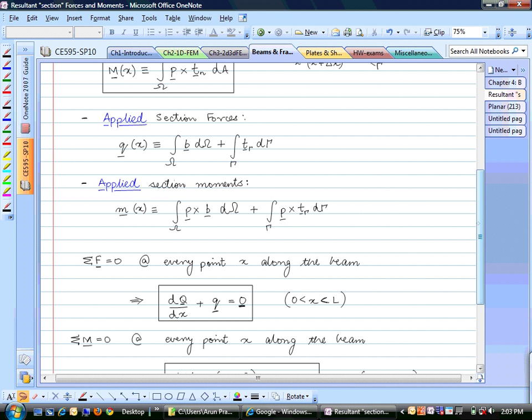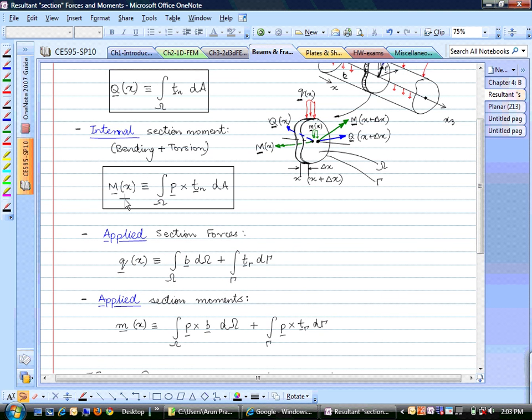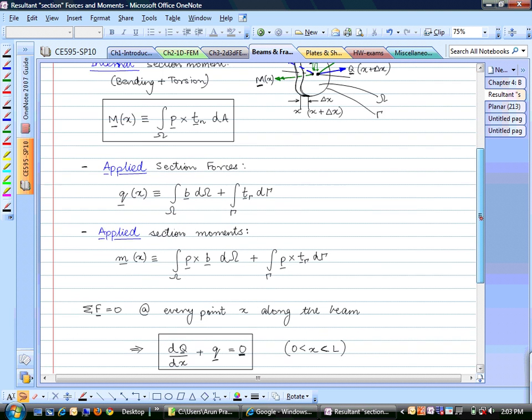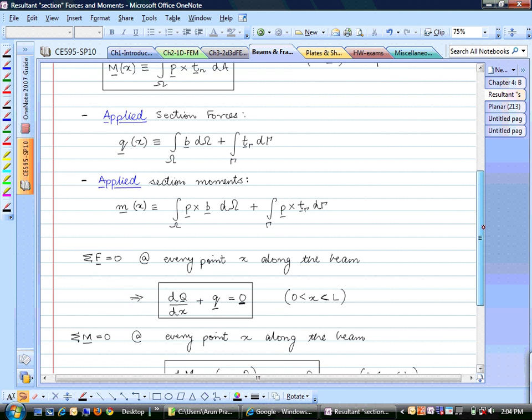Now what we have done is we have removed all of our variables that were coming from three-dimensional continuum mechanics. We have replaced them with these types of measures. Q is the measure of stresses, and Q and M are equivalent stresses in beam theory. So in 3 dimensions or 2 dimensions we had sigma, here we have Q and M. Similarly, you can also come up with measures for strains and for the constitutive material law. What does Hooke's law become?